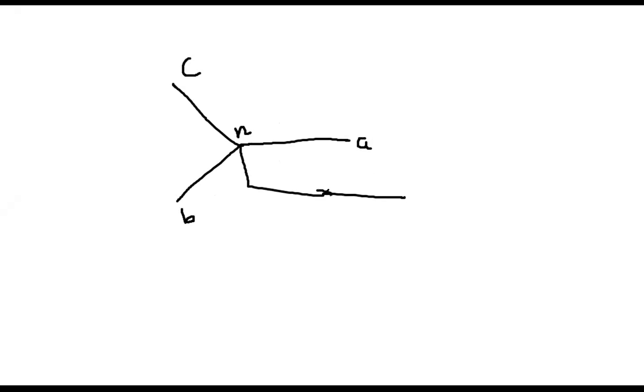Okay, so for example, this is one phase, this is another phase, this is another phase. This is a Y-connected system. This is A, this is B, and this is C. Then this point is the neutral point, and this is the neutral line that is going. So this is the IN current direction. If it is a balanced system, then there should not be any current flowing through this neutral line. IN should be 0 in case of a balanced system.